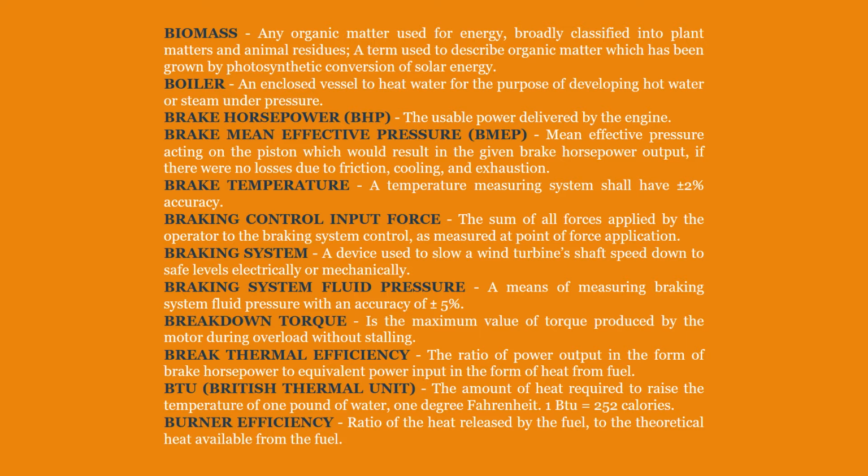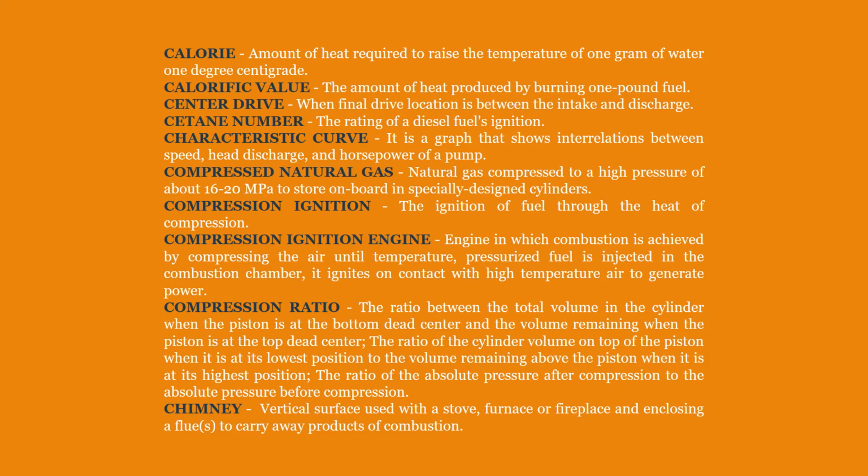Burner efficiency. Ratio of the heat released by the fuel to the theoretical heat available from the fuel. Calorie. Amount of heat required to raise the temperature of 1 gram of water 1 degree centigrade. Calorific value. The amount of heat produced by burning 1 pound fuel. Center drive. When final drive location is between the intake and discharge. Cetane number. The rating of a diesel fuel's ignition. Characteristic curve. It is a graph that shows interrelations between speed, head discharge, and horsepower of a pump.